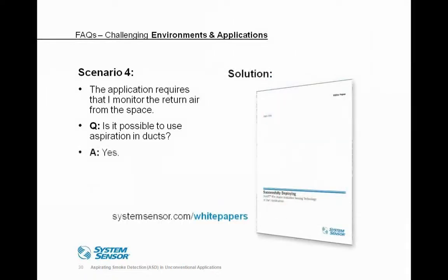And we do have online a white paper or application guide that will step you through certain things to look for when employing a duct detector. It may be the number of sample holes based on the size or height of the duct detector, if you're going to need a couple of sample pipes.